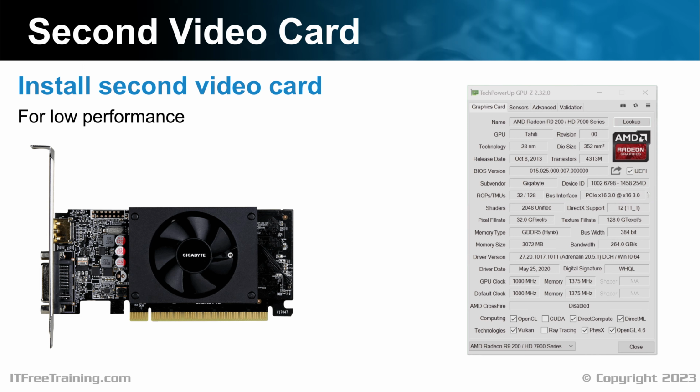Different motherboards will support a different number of lanes. What makes it more complicated is that some CPUs will have more lanes than others. This affects how many available lanes will be allocated to each slot on the motherboard. When installing a second video card for low performance, keep this in mind, as you don't want it taking resources away from the primary video card.